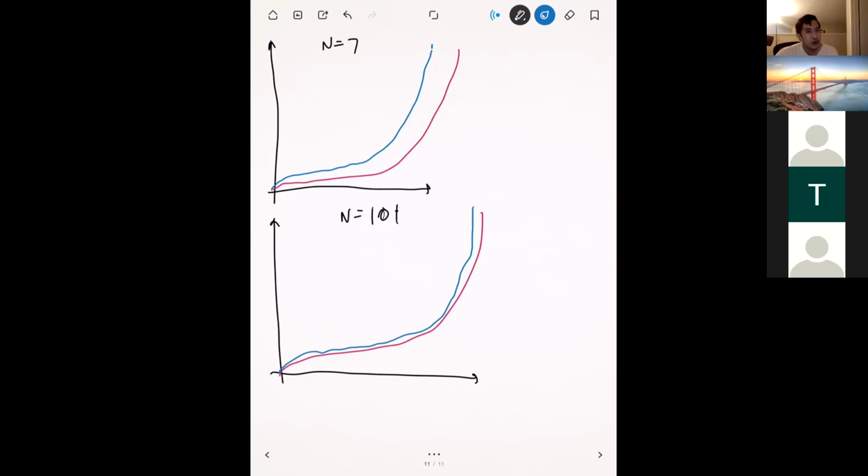I'm presenting this as a trade-off, but for this class, you won't really see it except for our 2D problems. Because for 1D, no matter what scheme you use or what the velocity is, you can probably kill it with enough nodes such that you'll get a stable solution. But for 2D and 3D problems, it is a real decision you have to make, because if you have a sophisticated 3D model, refining your grid might be the difference between your simulation finishing in 3 hours versus 3 days. And that's a real thing.